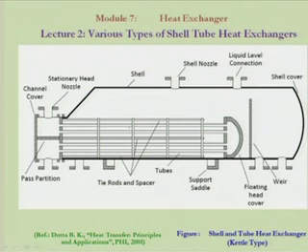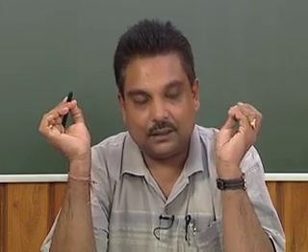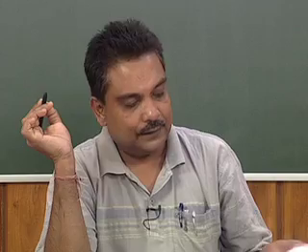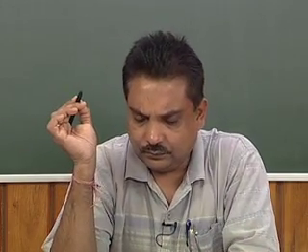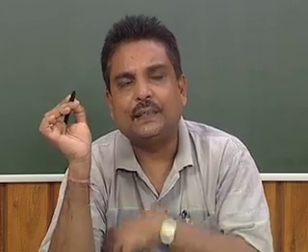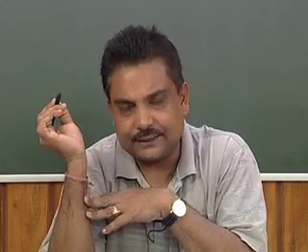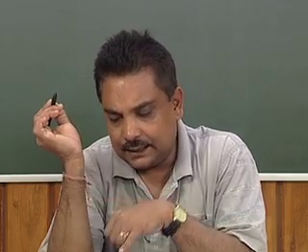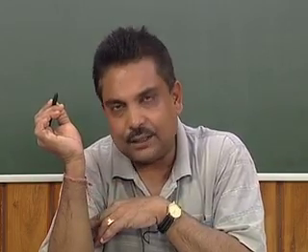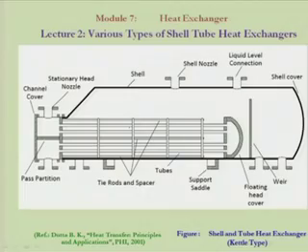We know that the reboiler is a very common thing for our shell and tube heat exchanger applications. So, reboilers are placed with a distillation column. At the bottom of the distillation column, the reboilers are placed, and we can see that these kettle type reboilers are used. Here it is again like a shell and tube heat exchanger, but the only thing here is this,